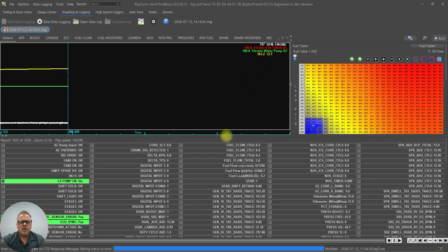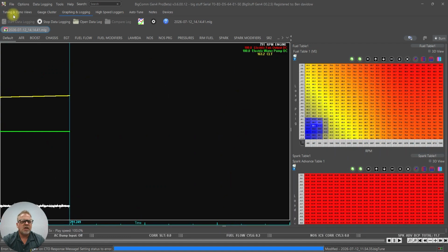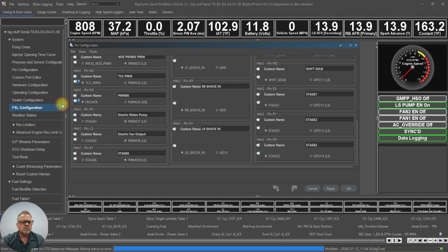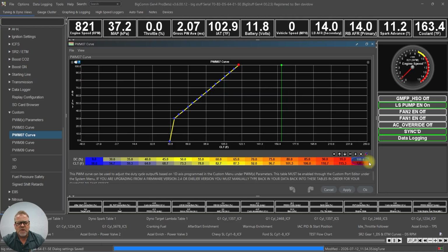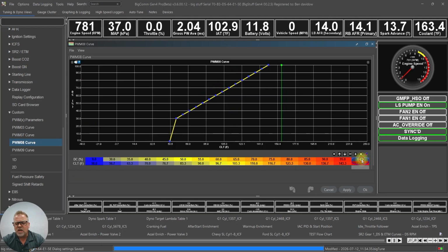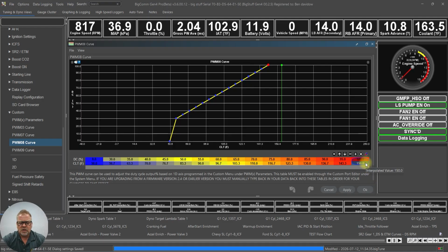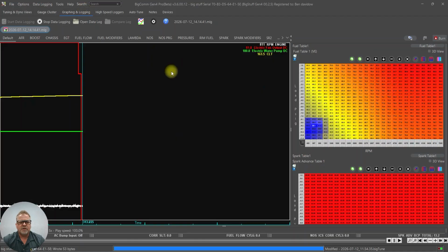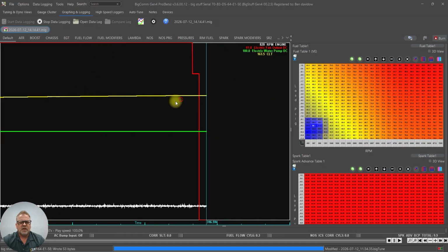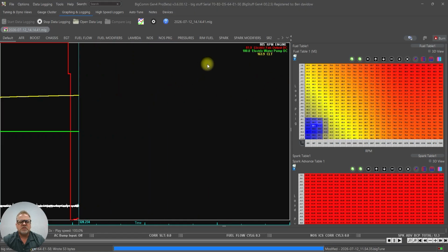Now, if I wanted to make some adjustments here and actually watch this stuff change, I come back over to tuning and dyno views, come back down here to the 07 curve, and we'll do the fan, for example. Instead of making it 100% at 150, I'll go to 200 degrees and then interpolate that out. All right, and then if I go back to my logger, you can now see that the electric fan has dropped and we're now maintaining around 82% duty cycle, and it'll start ramping up as the coolant temperature warms up there. Okay, so this is it in real time.